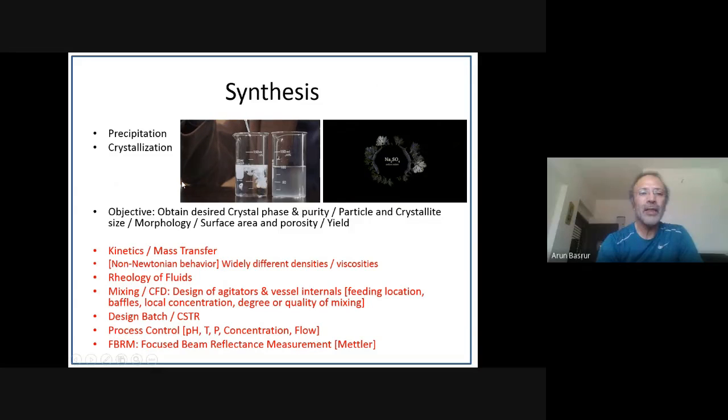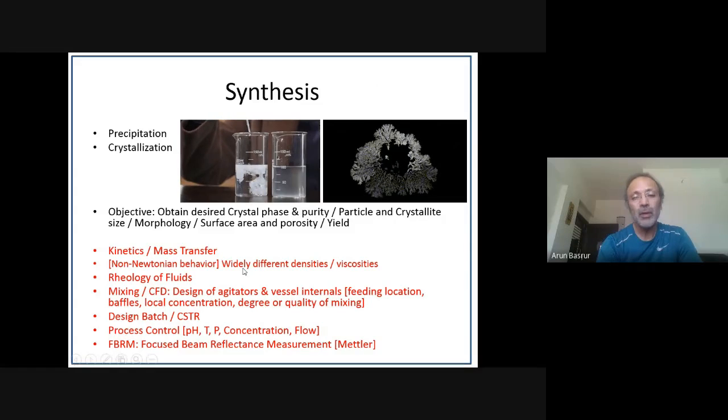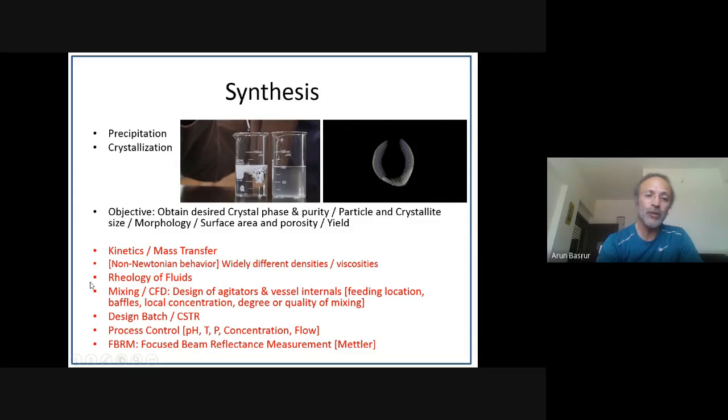In both cases, you prepare either a solution, a slurry, or a gel. These can have widely different densities and viscosities. And sometimes they could be thixotropic or dilatant, which is non-Newtonian behavior. So there is an opportunity to study the rheology of fluids. Now, studying the rheology is important in designing mixing equipment. CFD also helps in this.